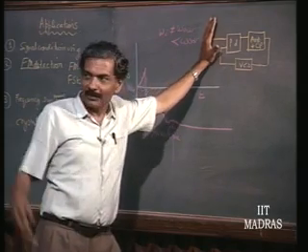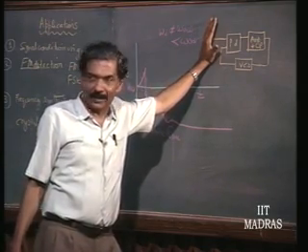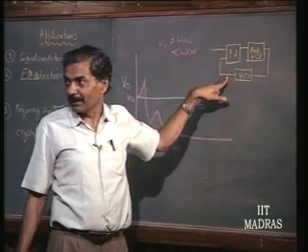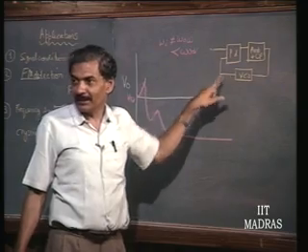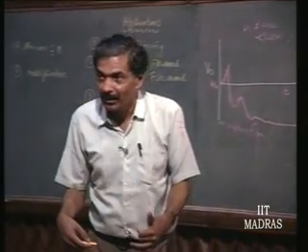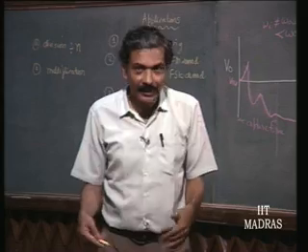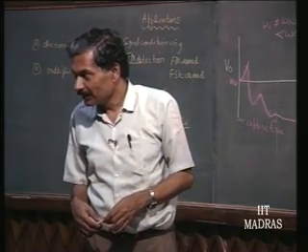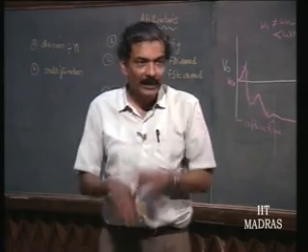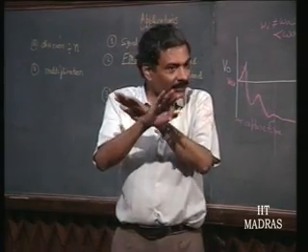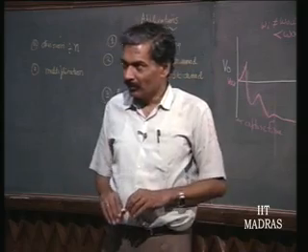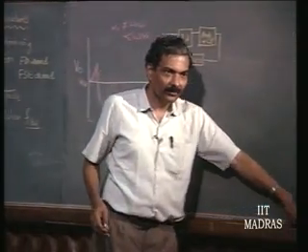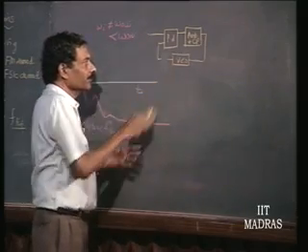Now, the same argument in the other way is also valid. This can be 1 megahertz, but this can be 1/3 megahertz. That is called subharmonic locking. So I can divide and multiply using this harmonic locking principle by any number. But this method is possible, but not in vogue. What is in vogue is this: we will design a VCO